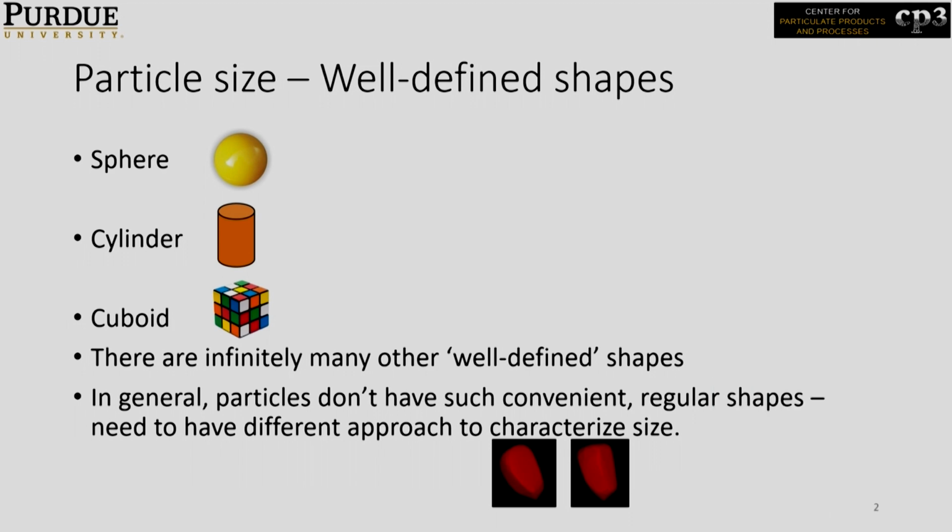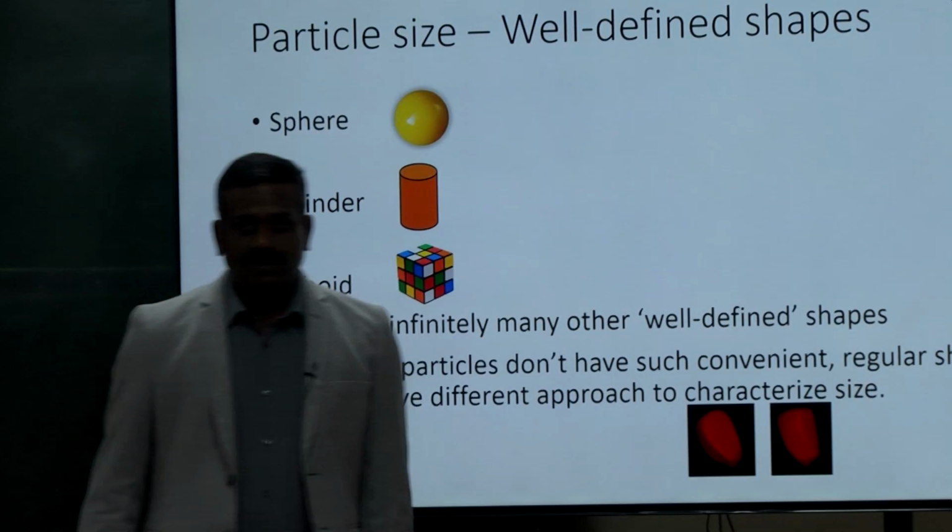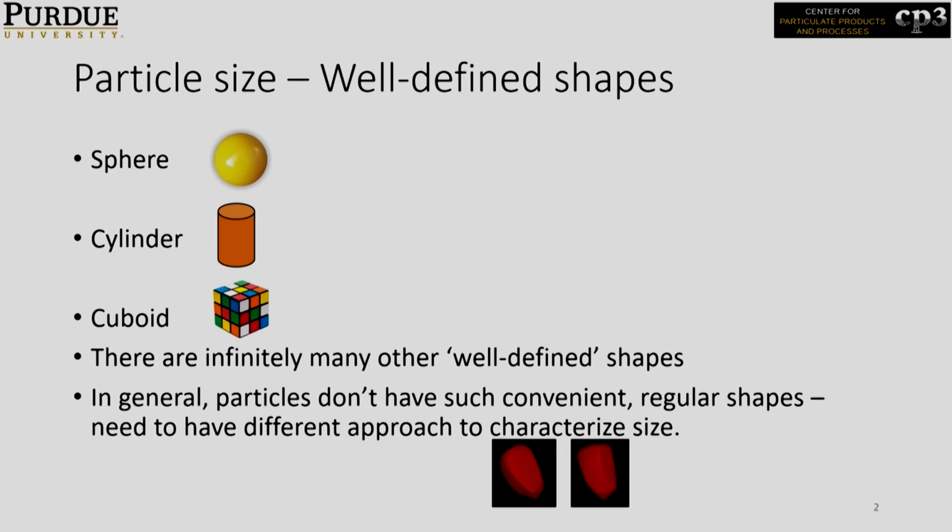So again, just an example of a kernel here. It's an X-ray tomography image of a corn kernel. So I put that in. We use these X-ray CT scanned images to develop corn kernels when we simulate using DEM modeling, to get accurate sizes and shape.